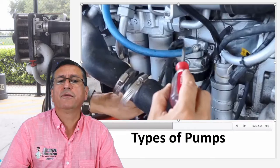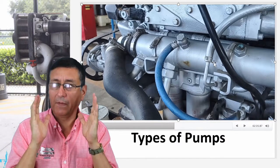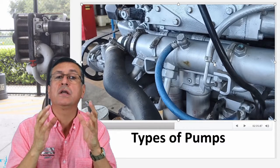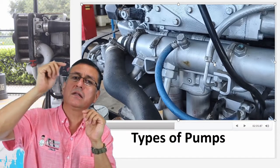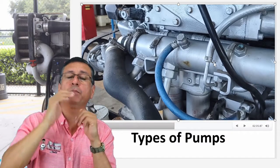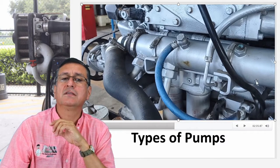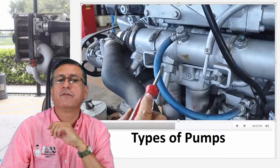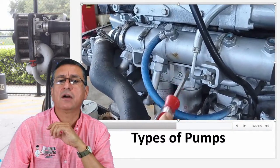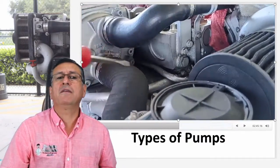Okay, the fuel goes out and enters this compartment. This compartment is the fuel cooler. Remember, the majority of diesel engines have a fuel cooler in order to reduce the temperature of the fuel a little and avoid the fuel entering the combustion chamber at high temperature, in order to avoid vapor lock. Okay, this is the fuel cooler. That's the input of the fuel cooler, and right now the fuel goes over there into the serpentine and continues here, and enters the manifold for the common rail.